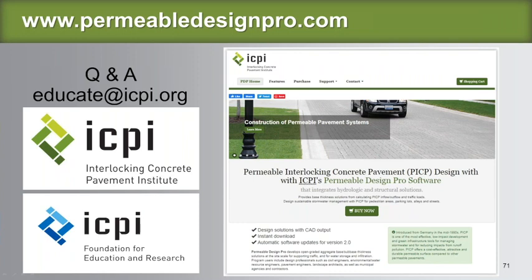That's fine. If you use those models and model permeable pavement, you will probably end up with a little more efficient, a little thinner cross section. However, those models do not do structural design. And like Dave said at the beginning, you model the hydrologic side of that nice flow chart, and then you do the structural design, and you end up typically picking the thicker of the bases. And so the strength of this program is that you get not just one, you get 2 slightly different design methods for calculating the structure to hold up the traffic.